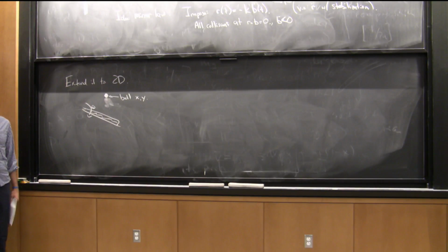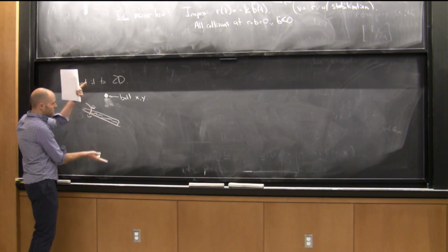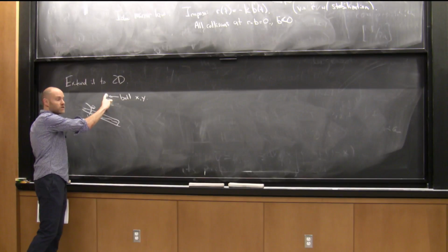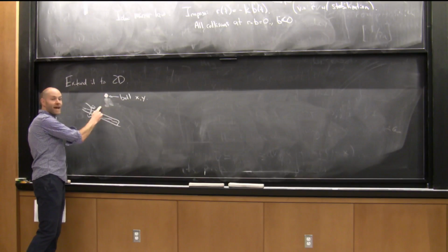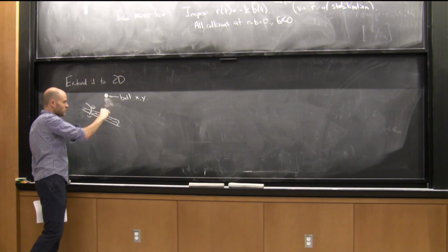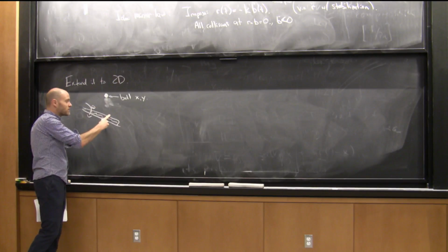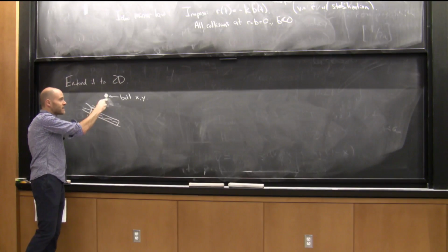Turns out the same mirror law idea can stabilize this. If I impose this to match, that stabilizes the Y dimension. And if I want to stabilize X, then the trick is to just impose one extra term. If you hit a little bit early, before it comes all the way down, then you'll move it this way. If you hit a little bit before the paddle comes back up, then it'll move a little bit this way. And again, a very simple mirror law can stabilize the two-dimensional.